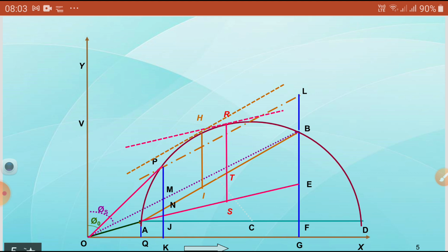Under no load condition, the rotor will rotate under normal condition with a small slip. Okay, so that is the rated RPM, maybe 1440 RPM for a 4-pole machine. Okay, synchronous speed is 1500 RPM. Our rotor is running at 1440 RPM. What is the reason? We have already seen in synchronous motors that synchronous speed and rotor speed are equal, but in case of induction motor, the rotor never reaches synchronous speed. Okay, that is the main difference between the synchronous motor and the induction motor.